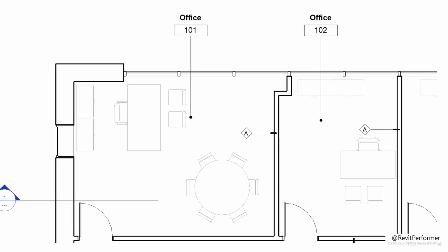So here's a commercial floor plan with a curtain wall, and the default wall joins will typically try to join to where this red line is that I've drawn on top here, which means that it would look something like what you see on the left-hand side. But if you use disallow join, you can manually modify it so that the wall butts into the mullion instead of the wall itself and get the proper condition. So that's a more common example of when you would use that disallow join.